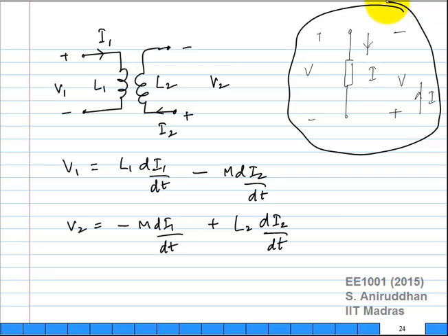When you analyze the circuit, the answer you get will be minus 5 amperes, which tells you that the current is actually flowing in the opposite direction. Again, that is the whole point. These are basically symbols standing in for the actual element, and you are choosing certain representative directions. You can choose any direction you want, as long as you are self-consistent for that particular element, and everywhere in all analysis you choose it in the same direction, your solution will be correct.